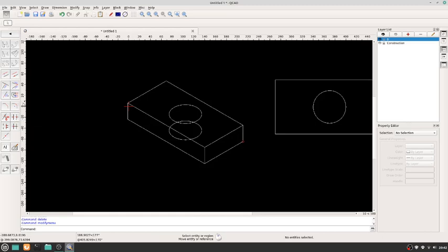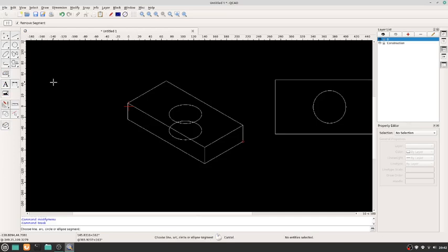I'll do that actually. I'll go back here. If I type in D2, the tool's ready to use, and I didn't even have to click on any of these toolbars. So rather than clicking twice or taking my mouse all the way over here, if I'm over here, and clicking on that tool, all I had to type in was D2 and the tool's ready to use. So I'm going to remove some of these segments I don't need, so it's just that bit that's visible, and